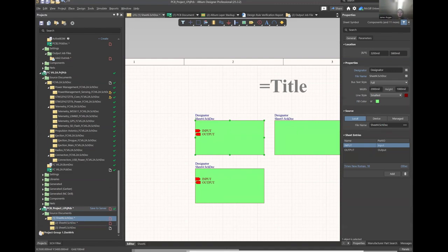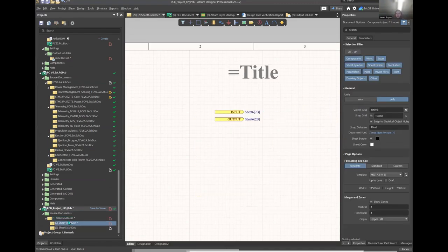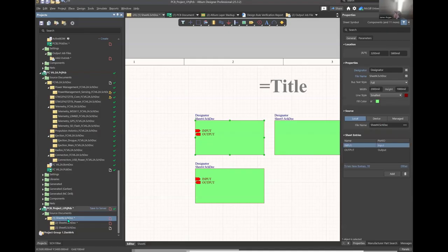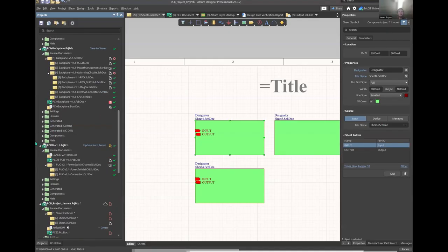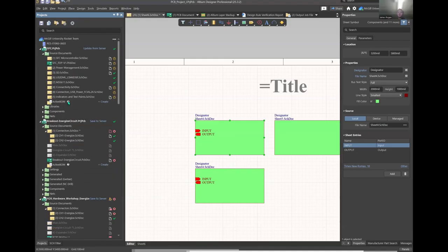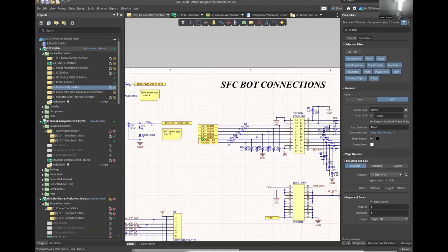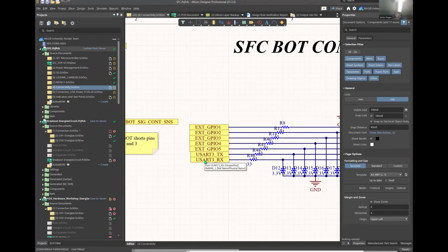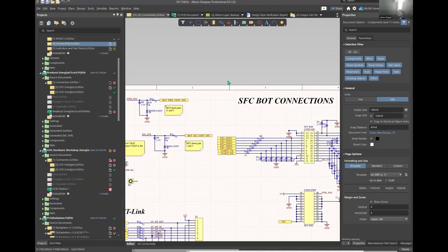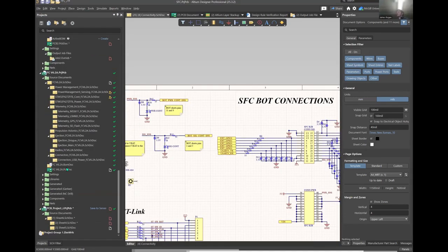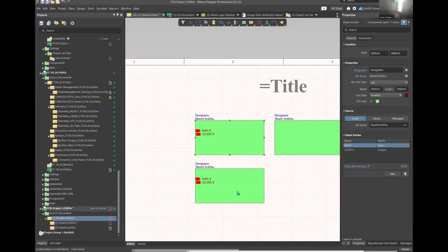So this port here is only on this circuit, and the only way to access it is on this sheet symbol. If you had every project in one top level thing, which I don't recommend doing, then the ports actually just port across to all the different sheets. So in this person's design, if you have a port here, this port is accessible to all the other sheets in the design. But this is kind of unclear as to where things go. So I'm just introducing hierarchical design at the start, just so that everybody gets in a good habit of it.